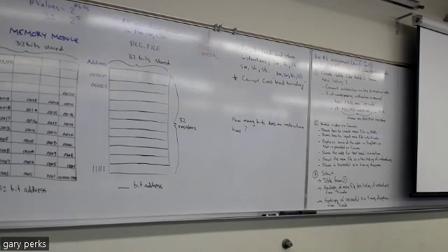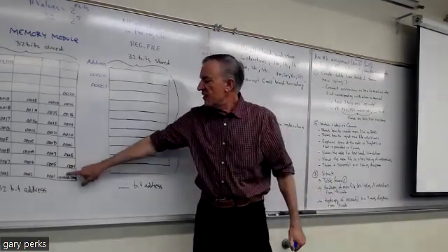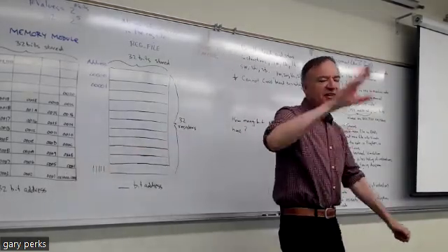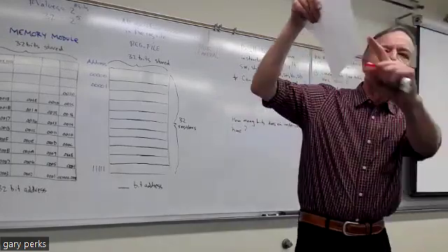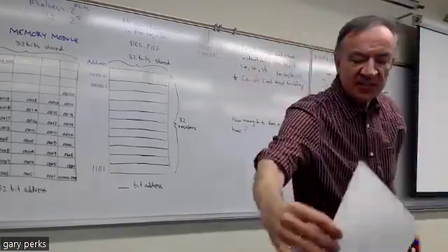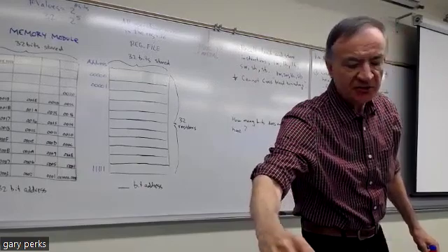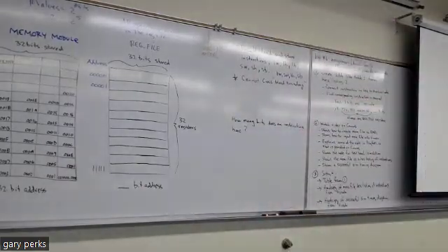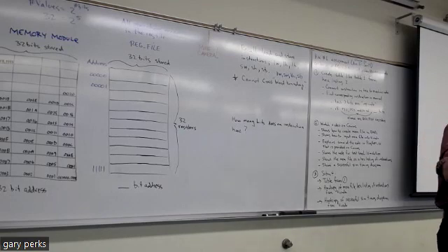I think maybe the answer to your question is something you're going to get to next class. Determining the address of the instruction that we're going to use is another component, like on this diagram, it's this PC, this program counter. That's providing the address to the memory module in order for it to know which instruction to use. And we'll talk about next time how we always reset that program counter so it's always accessing instruction 0, the instruction at address 0 first, and then from there, it just increments by 4s.